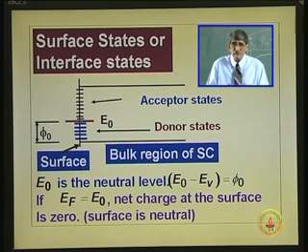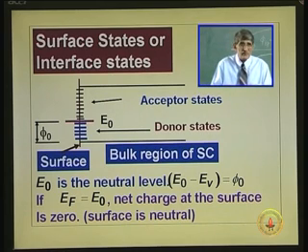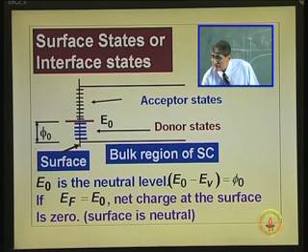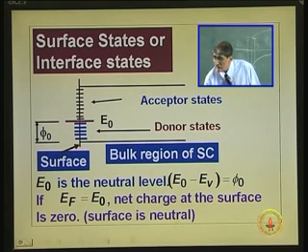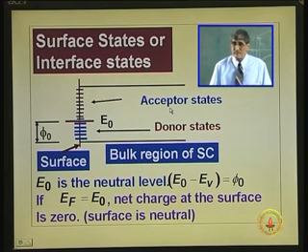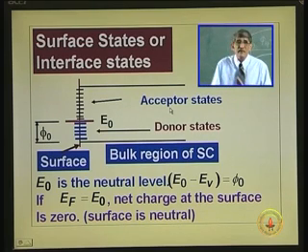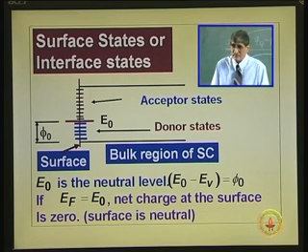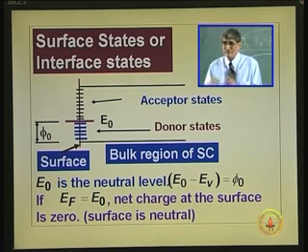Why do you call the dangling bond a level which is distributed over the band? All the levels above that you call acceptor states. The same dangling bond behaves like an acceptor state, and like a donor state. It is not the same one; it belongs to a different atom.